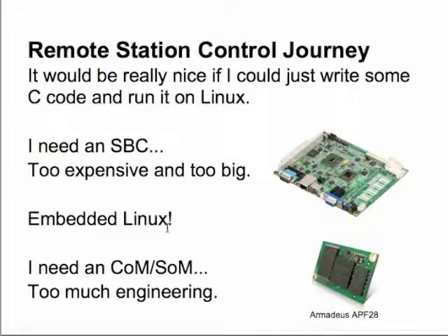So I looked at single board computers. They were usually too big and too expensive, usually made for industrial type applications, and relying on a certain form factor. So embedded Linux is where I wanted to go, so I looked at computer on modules and systems on module devices, which provide a CPU and a bunch of peripherals and then a header.